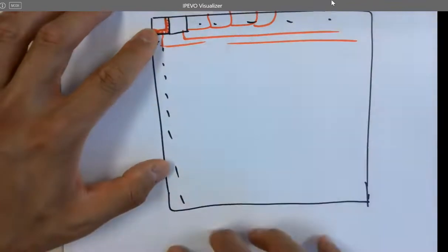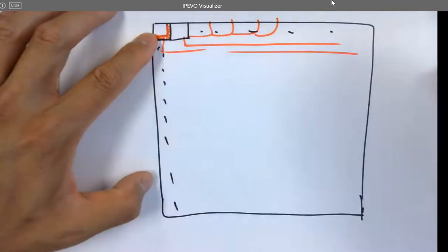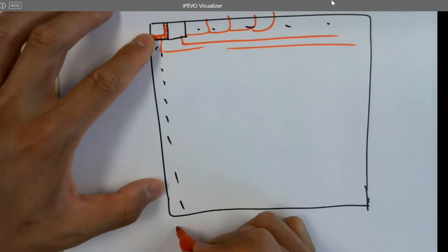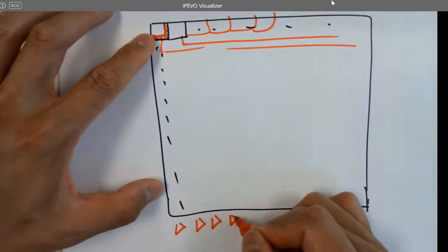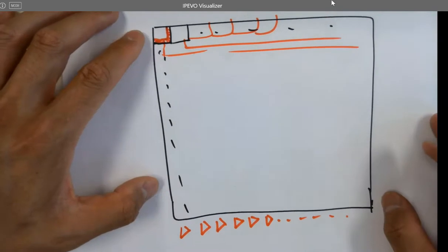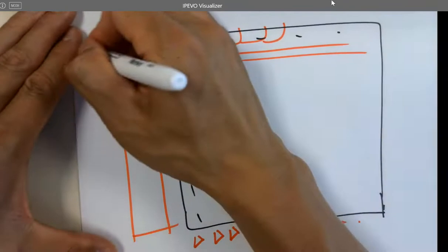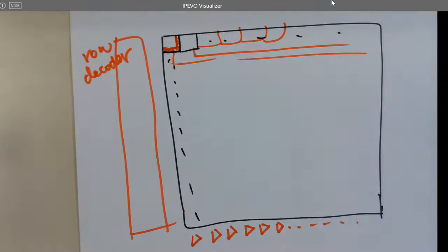But usually how many OpAmps do we have? How many TIAs do we have for the whole image sensor? It's usually just at the very bottom, right? You have 1 for each column. And that's it. So what's happening is you have a row decoder, which is a very simple logic circuit.